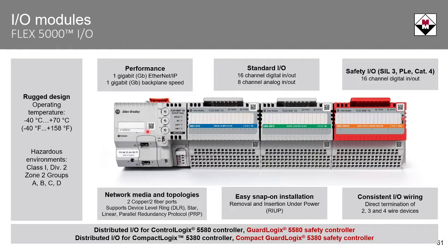Analog modules support 16-bit resolution, individual channel alarms and scaling, as well as current sourcing for the analog output modules. Please note, you must order a base, the appropriate removable terminal block, and the desired I/O module. One other nice feature is that these modules can be removed and inserted under power.